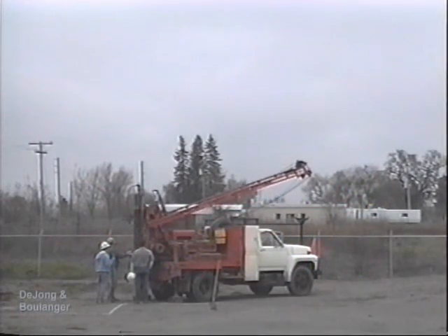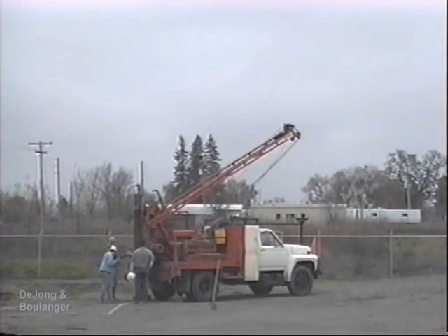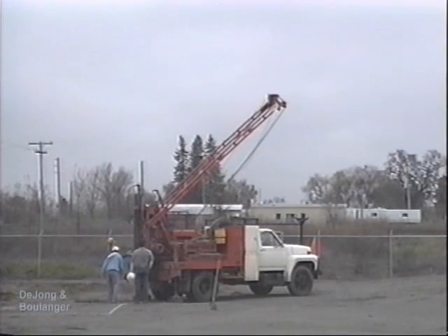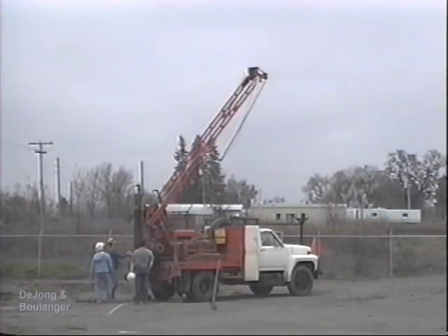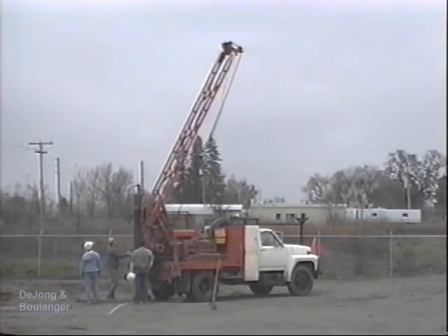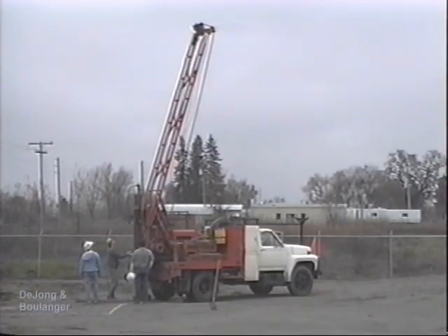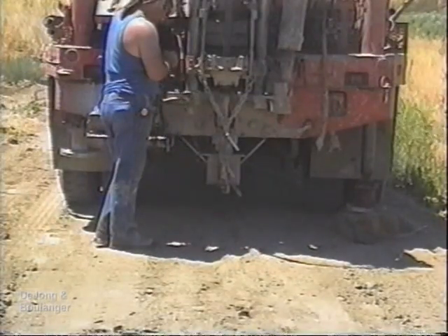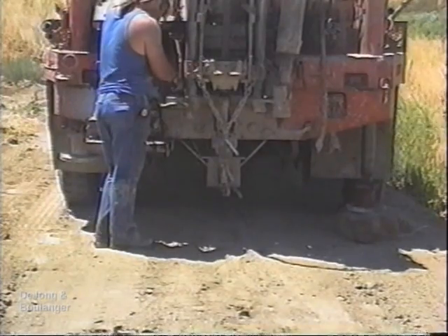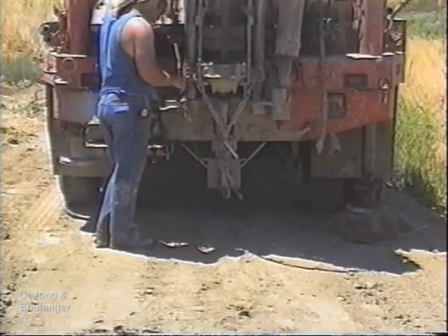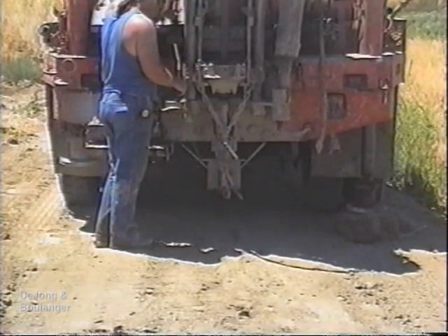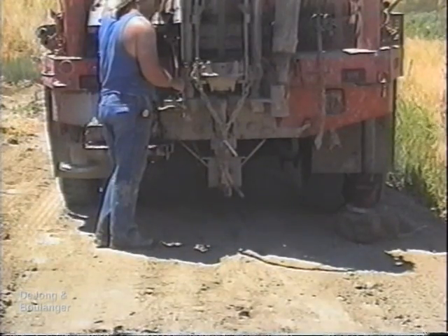Here, a highway drill rig will be used to demonstrate the general features and procedures that are common to all drill rigs. After the drill rig is positioned over a borehole location, the mast is raised and secured and the drill rig is leveled. If the rig is not level, the borehole will be angled, causing great problems in drilling and sampling, in addition to producing an inaccurate soil profile.